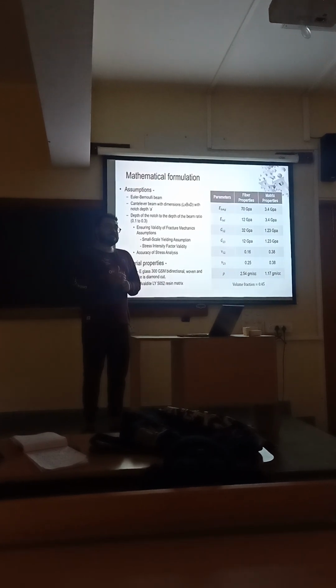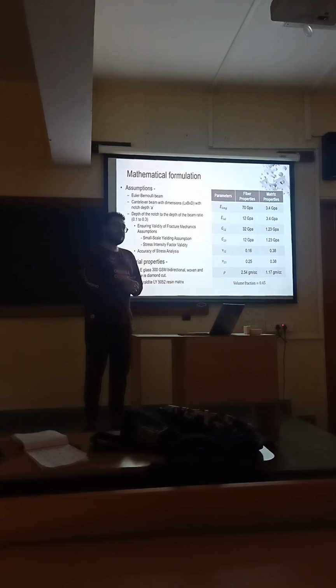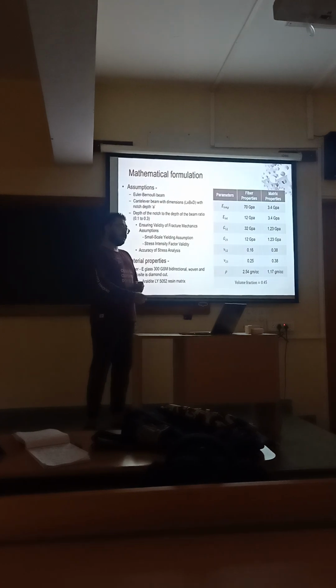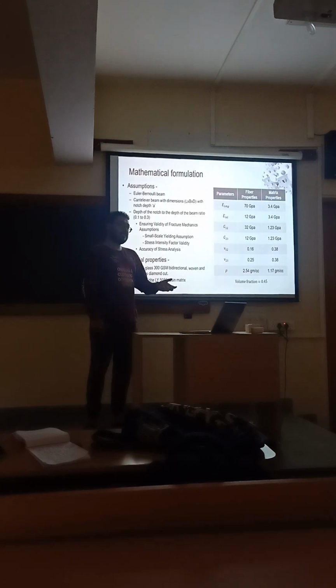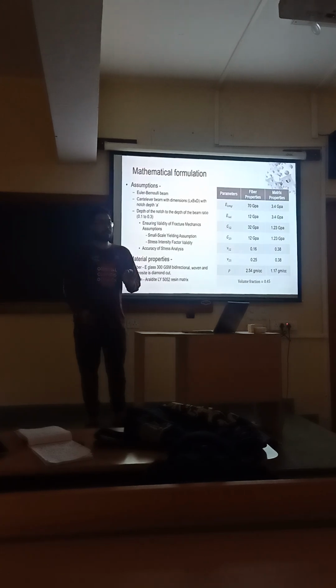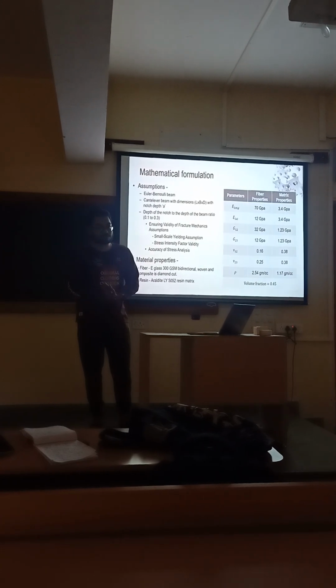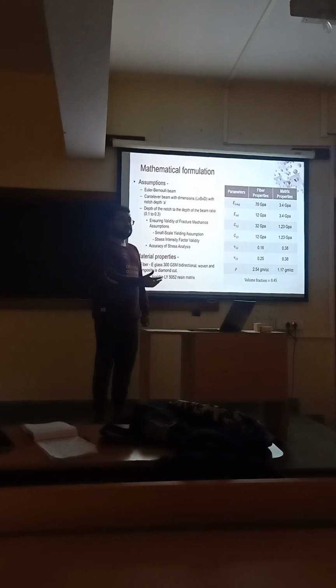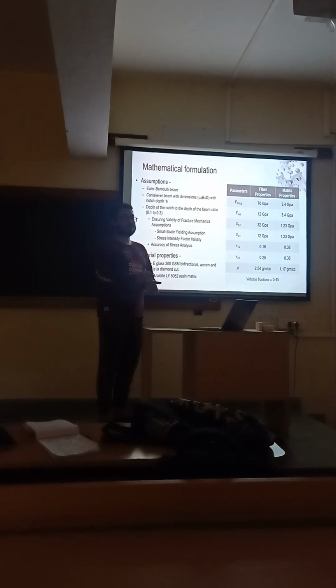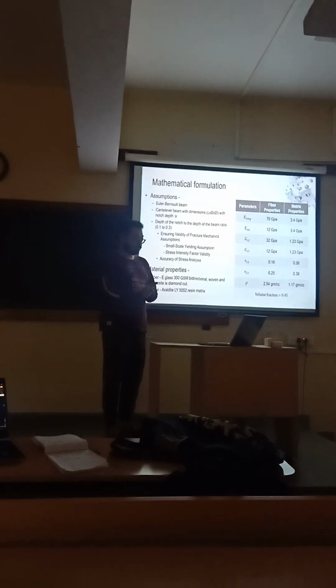When we apply load, the plastic region will be so prominent that we will not be able to apply linear elastic fracture mechanics. One of the major assumptions is Hooke's law. It will not be applicable in that region. So the notch depth is constrained to this range.